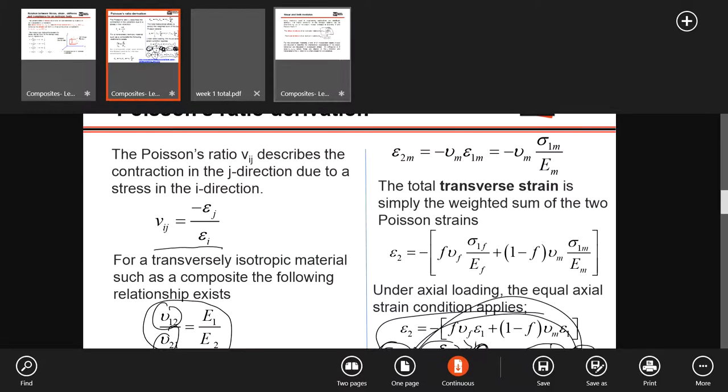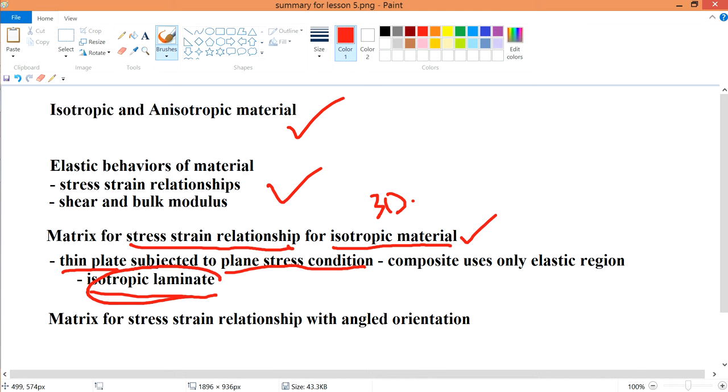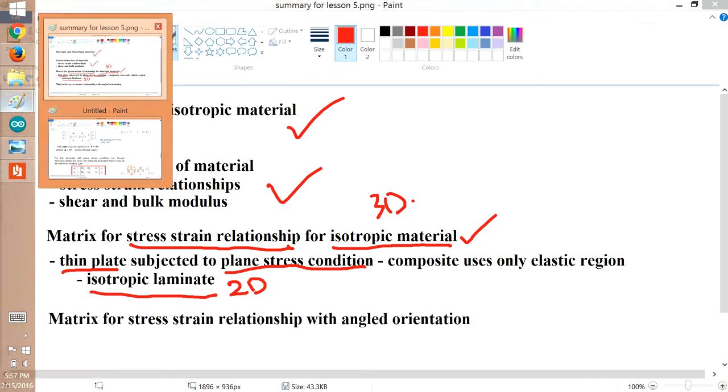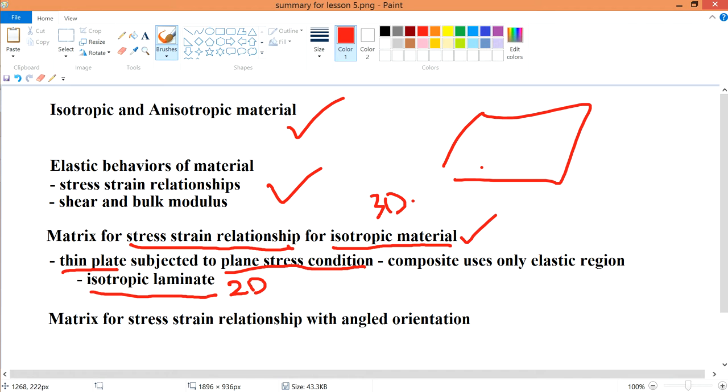And therefore that's the isotropic laminate, and please do not confuse it with an isotropic material. An isotropic laminate is 2D, a material is 3D. The isotropic 2D laminate is talking about a randomly aligned short-fiber material, in other words a plate. You have all your fibers randomly aligned and these fibers are short, because you can't have long fibers random like this. You can't have fibers merge like that. I don't know, maybe you can, but at least you get to know the different stuff already.